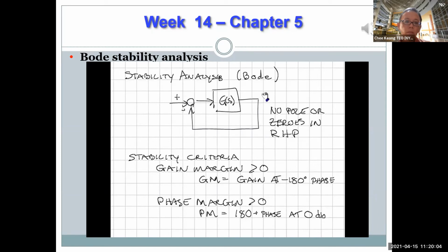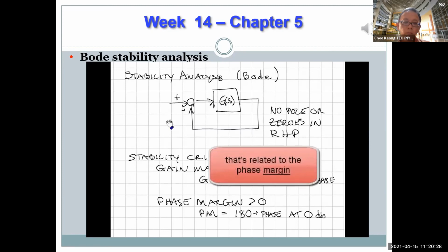The other thing you have here is something going in and coming out, and then you're subtracting it. As long as when you subtract it, it becomes less. The problem is that when this phase shift changes more than 180 degrees, a 180 degree phase shift is like a change in sign. So if you put in a positive number here, it comes out negative, then you change the sign again to subtract, it becomes positive, you add it back in, you can see it keeps growing and growing, and that's related to the phase shift.